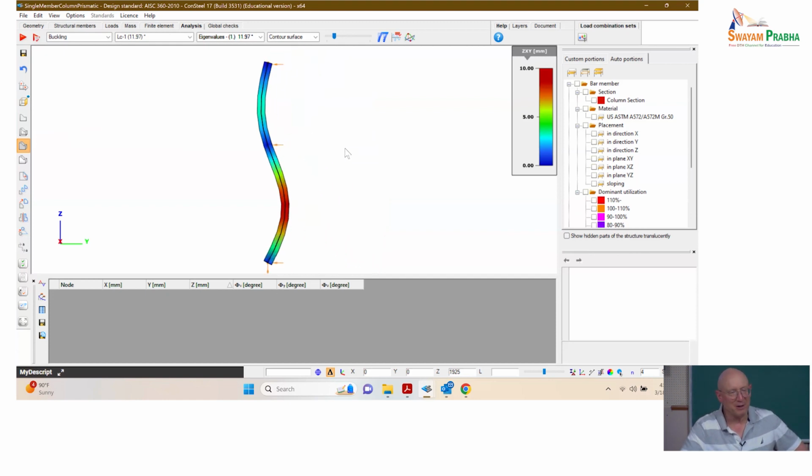So it's buckling out of plane in a braced buckling mode, and we're basically restraining displacement at the girt location from the girt and the flange diagonal to the inside flange. So that's how it's failing under concentric axial compression.